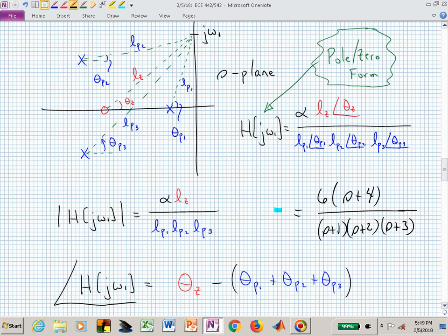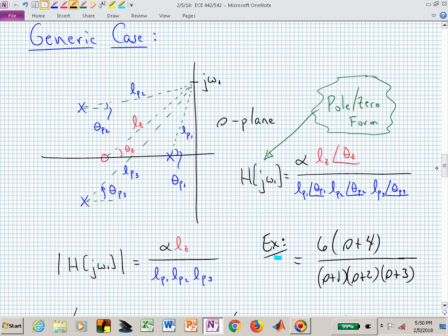And that obviously then impacts your magnitude at a given frequency. If somebody changes the frequency of oscillation, you simply do this process, except now you change where you're evaluating. Maybe it's now at that location, which is 2/3 of the original omega. But you now draw these lines and angles to that yellow highlighted point, and that's now the oscillating frequency you're exciting the system with, omega sub 2.